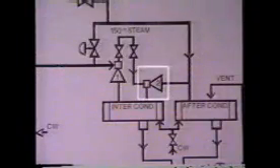To start up the vacuum system, the outside operator opens the steam jet valves. In this system, the valve to jet number 2, which is the jet farther from the column, is opened first. The steam jets have to be opened slowly to allow the system to warm up. This prevents damage to the equipment from rapid thermal expansion. He lets jet number 2 run for a while to draw most of the air out of the column. This jet by itself will not create a sufficient vacuum in the column.